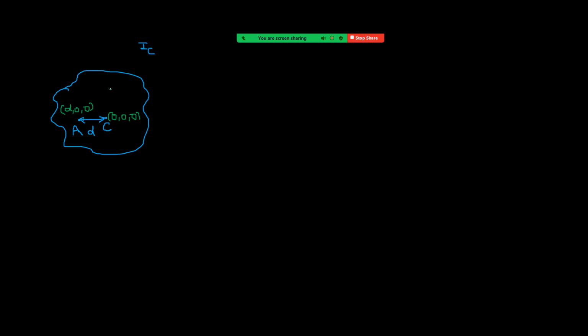Okay, let us take one point mass somewhere here. Its mass how much? Dm. Okay, and its coordinates, x comma y comma z. Okay, so we want to calculate now moment of inertia about an axis passing through point A. So, we want to derive relation about A, that is I, it is equal to IC plus m into d square, where m is mass of the body, d separation between these two axes.